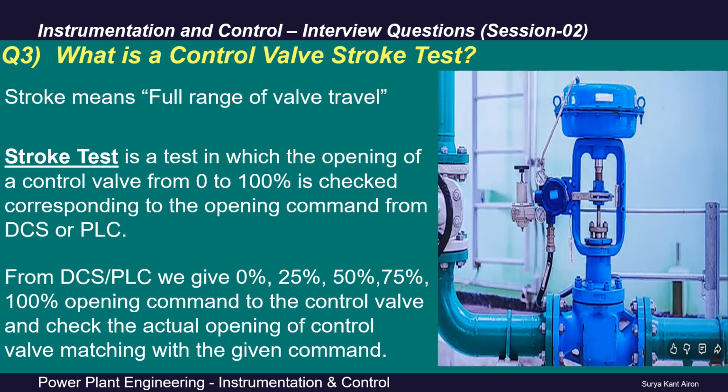Friends, this stroking test we generally do during our commissioning phase and during maintenance. During our stroking test, our positioner is also tested, that it is properly acting and positioning the control valve to the accurate position in line with the opening command received.